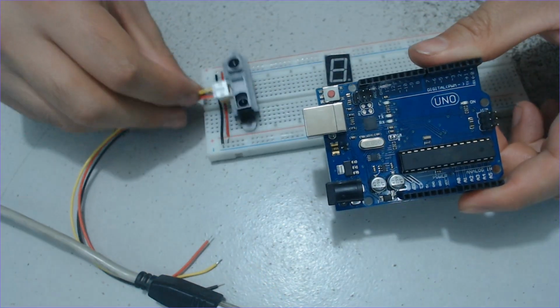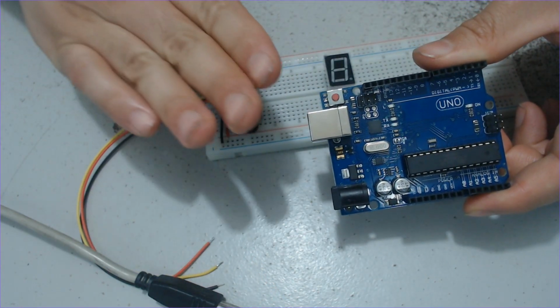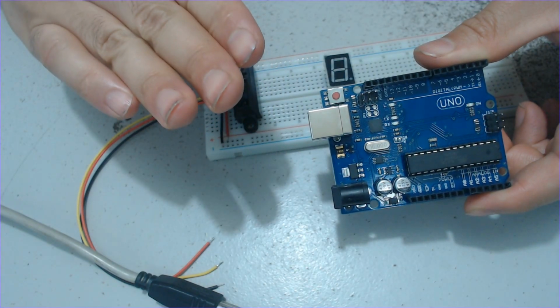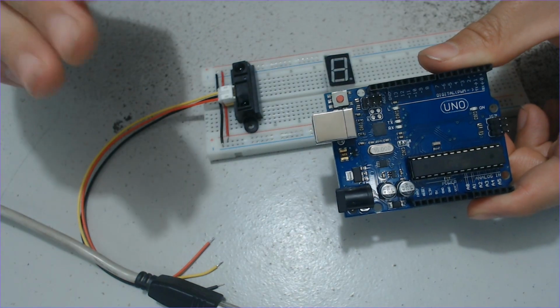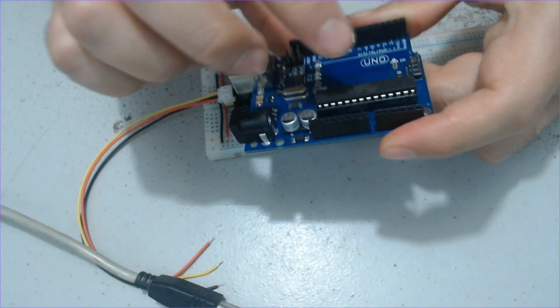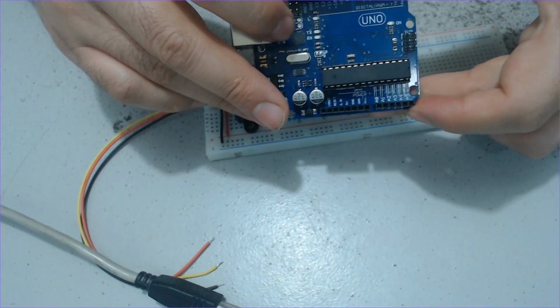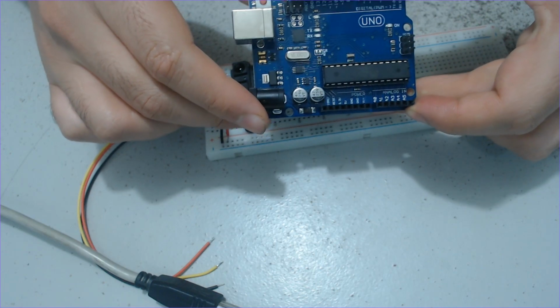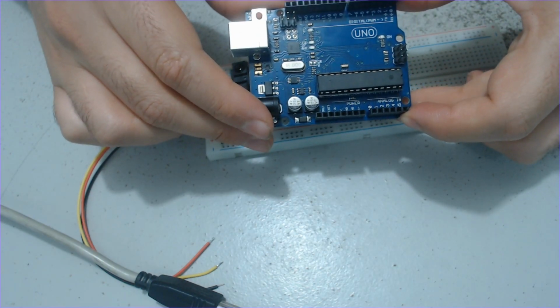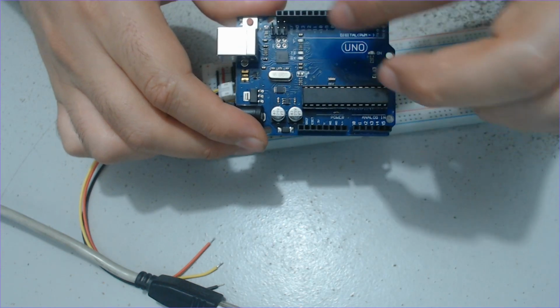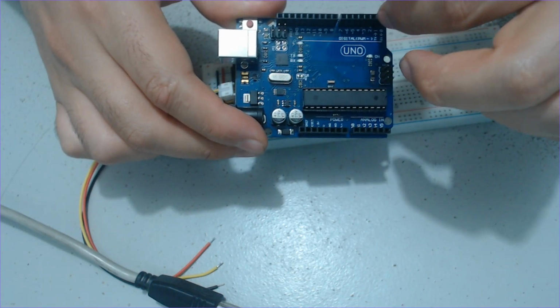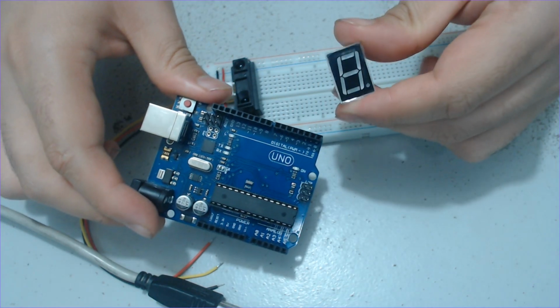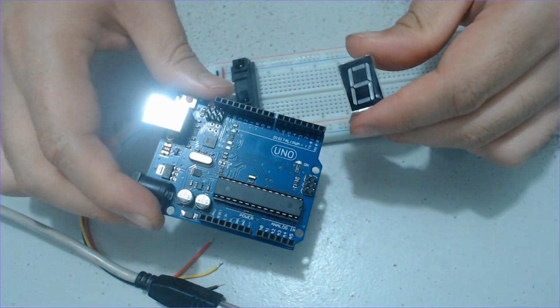So the infrared sensor is going to detect an obstacle, it's going to provide a measurement of the distance from the sensor to the obstacle to the analogical input in my Arduino card, and then we are going to send this data using the binary digital outputs to control my 7-segment display.